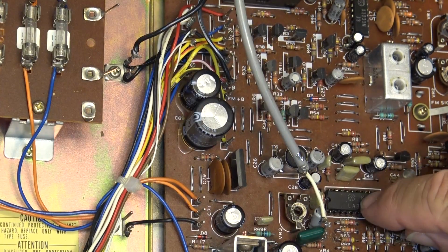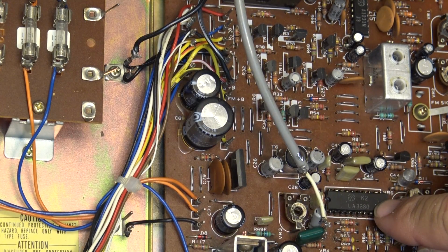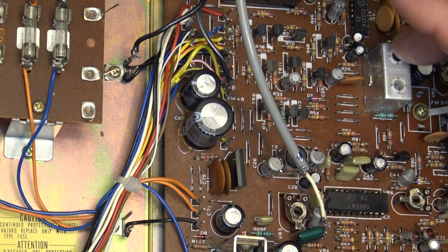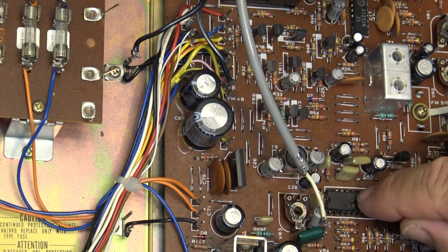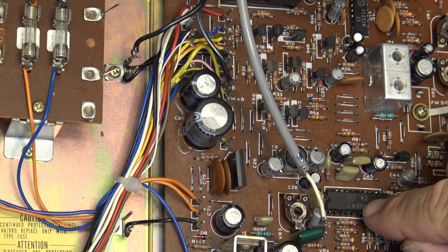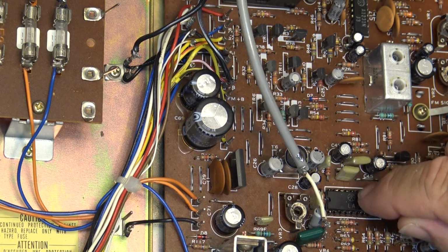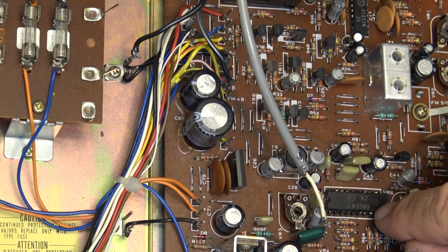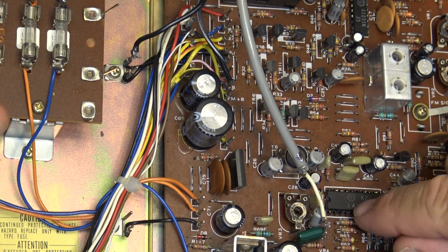This is actually the stereo decoder chip. And this is the input. I believe that's the stereo decoder. Yeah, the IF is over here. This is the stereo decoder chip, and this is the input to it. So, same information is going to the stereo decoder, but this is only tuning in the 38 kilohertz stereo information and providing you the left and right. So we just tapped into it to take it off.